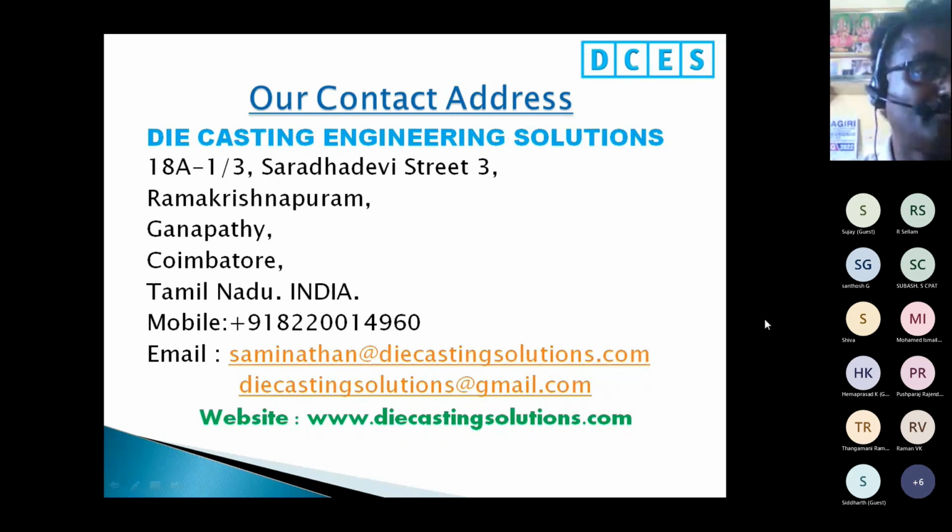For that, you need to have thicker biscuits, but it is not necessary to go more than 30 or 35 mm. Otherwise, what will happen? You will lose material, and also the plunger will need more pressure to push the biscuit out from the fixed die. So this is all based on your casting requirement and the die design.